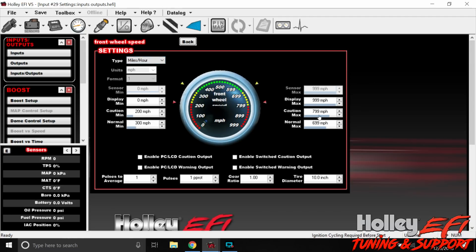We've got minimums and we've got maximums, and then here, okay, this stuff's all important. So like for a front wheel, your tire diameter, say a Mustang or something, is 26 inches tall. Pulses per rotation, I think he does the majority of them at 32, which is great resolution. And then there's no gearing, so it's 1.0.